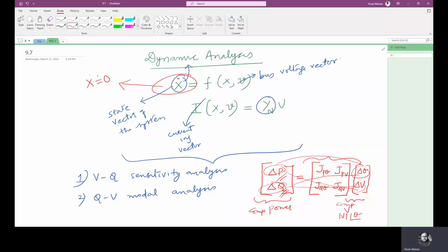So this may distort the information on stability condition of the system. The buses selected for QV and PV analysis must be chosen carefully, and a large number of PV and QV curves will be required to get the complete information on voltage stability of these buses.